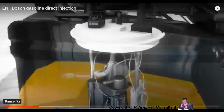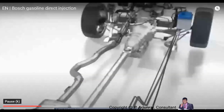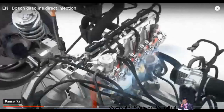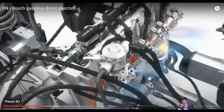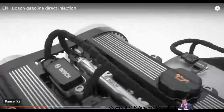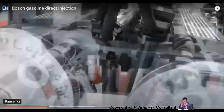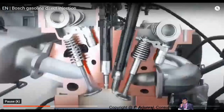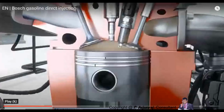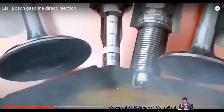So it has the fuel supply module, fuel tank, accumulator, distributor, and injector. Based on the electronic control unit signal, it injects the fuel based on the speed of the engine. So the fuel pressure gets varied with respect to the different speeds, different RPM. This is how the compression is going to take place. You can see it.